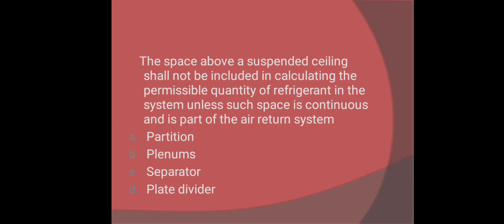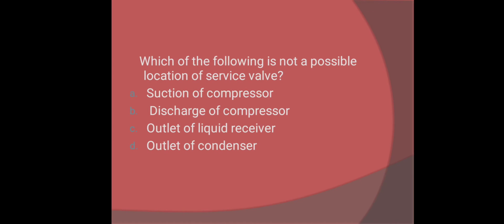Next, the space above a suspended ceiling shall not be included in calculating the permissible quantity of refrigerant in the system unless such space is continuous and is part of the air return system. Sagot natin dyan ay plenums. Which of the following is not a possible location of a service valve? Okay? Sagot natin dyan ay outlet of condenser, letter D.